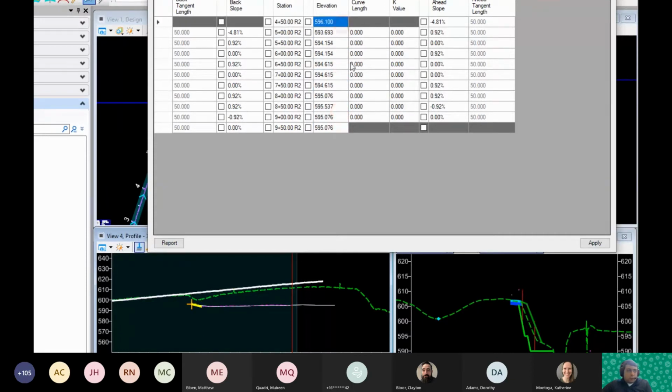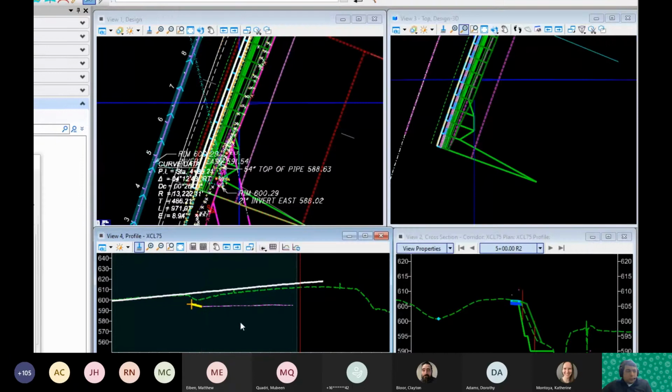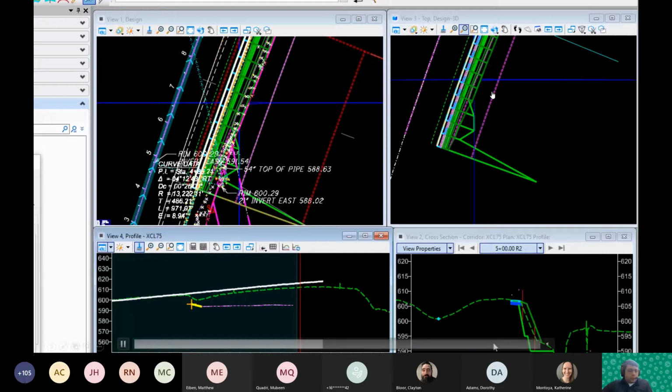So the cool thing is you're kind of managing it not cross section by cross section now. It's more dynamically linked together, if you will. So it's easy to come back and change a given vertex, and you can click on that line too and just change a given vertex elevation as well. But I think that table editor could definitely help speed up some of the input time.